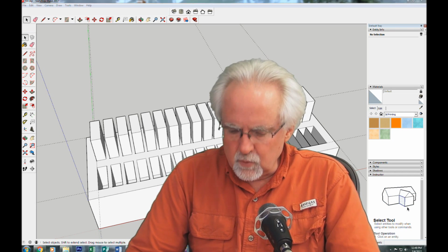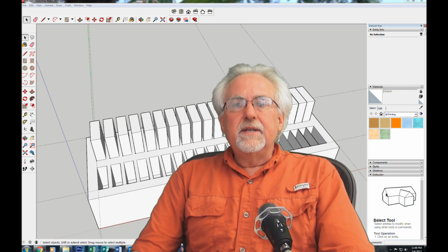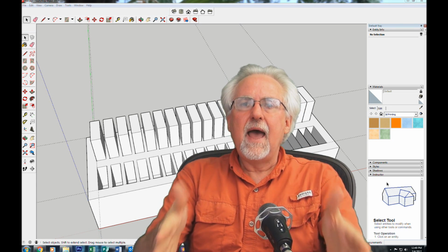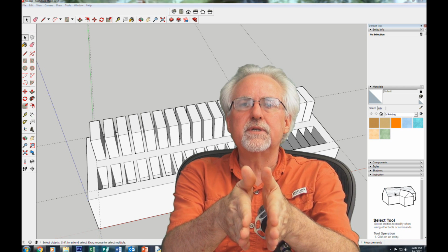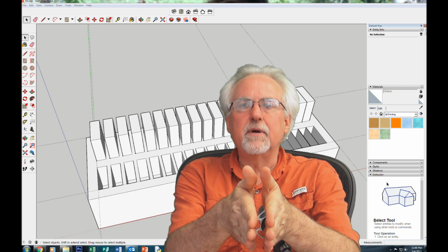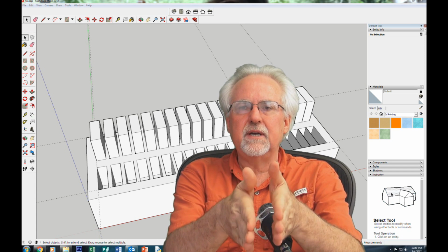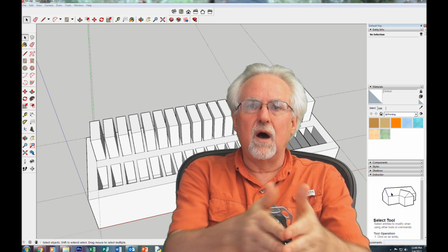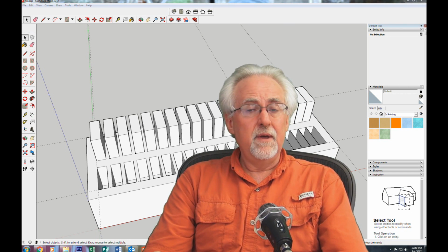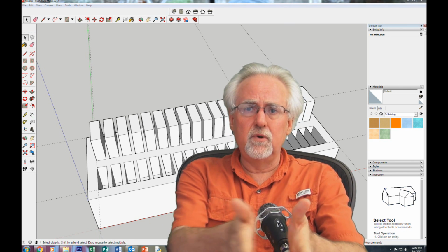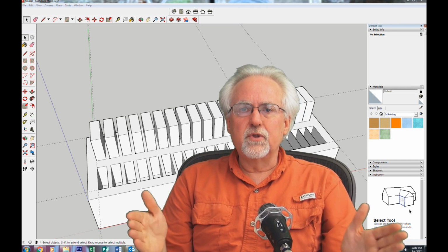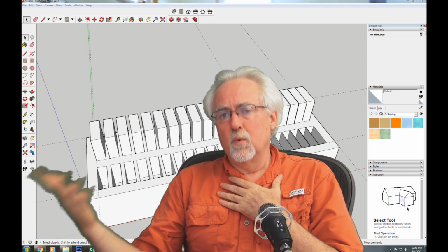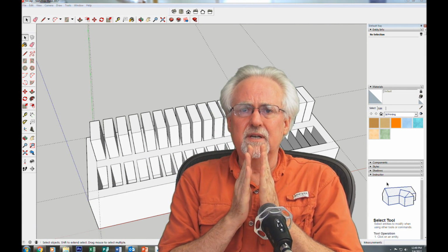So what are design rules? Well, let's think specifically. Let's say that as a designer, you want to build a column. The question is, how close can you put 2 columns together to where when you fabricate it, they remain 2 distinct columns? Because you could in your design software put 2 columns that were 1/1000th of an inch apart, but when you're going to fabricate them, you're not going to have 2 columns, you're going to have 1 column. So the question is, how closely can you space 2 things in your design where when you fabricate them, they will still be 2 distinct objects?